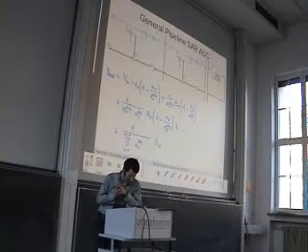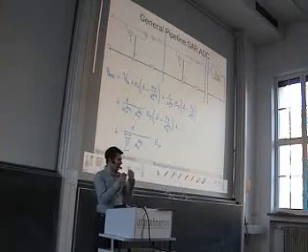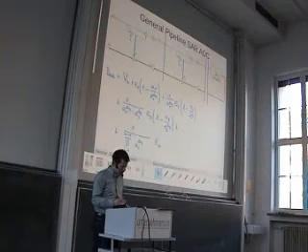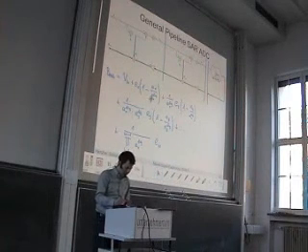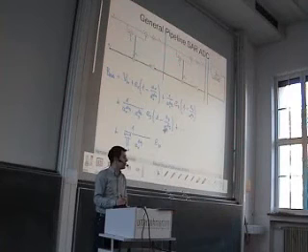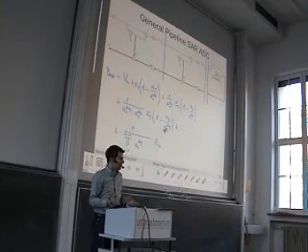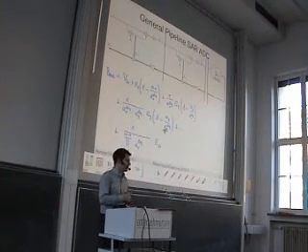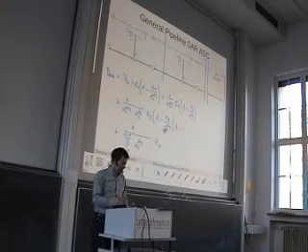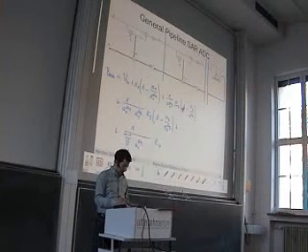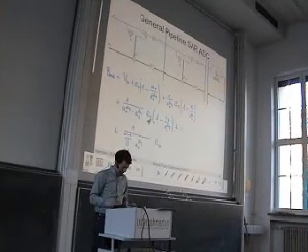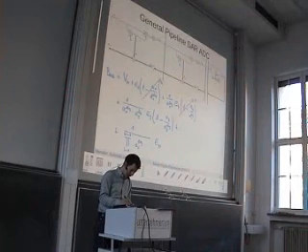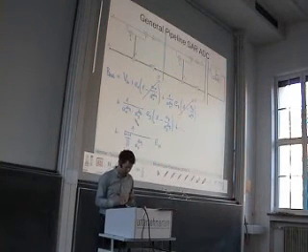But we can see in this formula, as soon as the A and the corresponding A digital, so the gain in the analog and the gain in the digital domain, as soon as they match, so if these two and these two and these two are equal, then all the intermediate terms vanish. This is our goal. We have to achieve the matching between the analog and the digital gains. And then they cancel out. So this one cancels out, this one cancels out, and this one cancels out. So this goes to 0, this goes to 0, if we achieve this matching, okay?